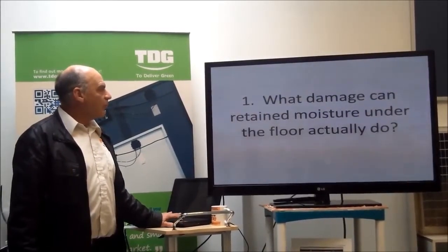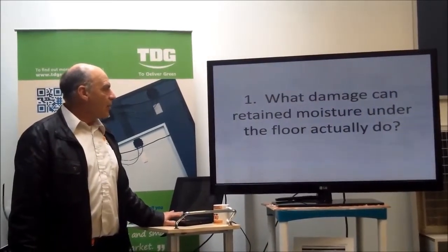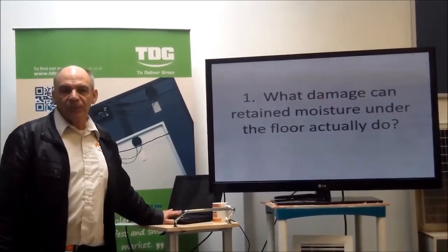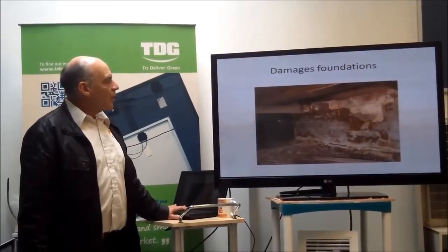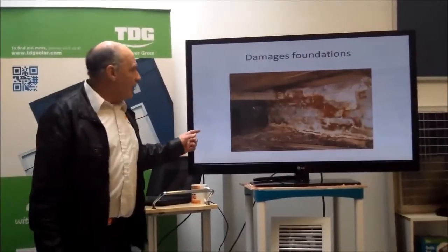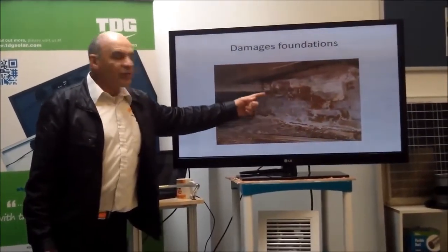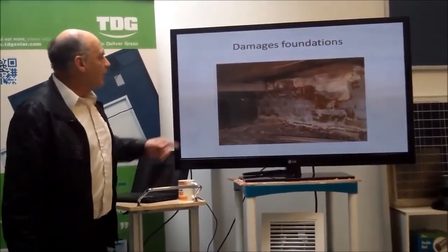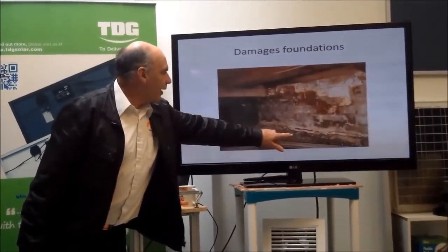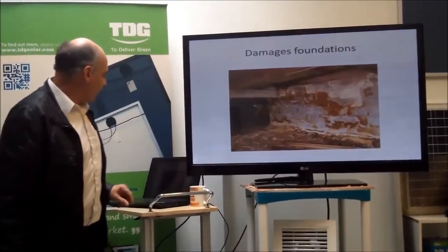What damage can retained moisture under the floor actually do? This is an example of damaged foundations where the bricks here have all started to corrode from the moisture coming up through the ground and being absorbed up through the foundations.